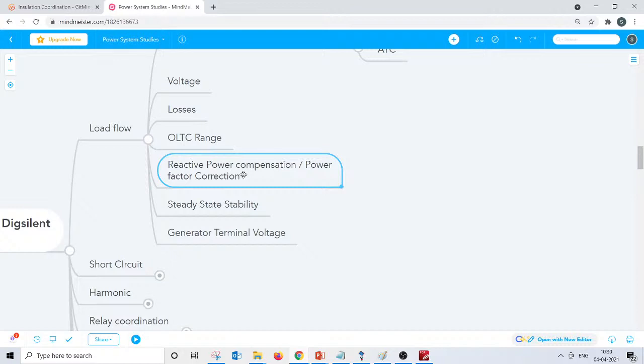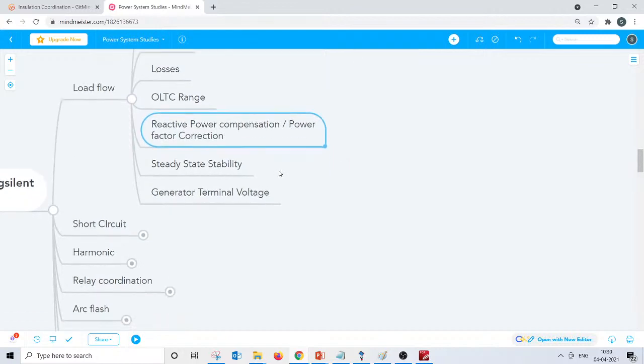Approximately, if you have 4 or 5 kilometer cables, it injects a huge reactive power in the 400 kV. So probably you need to make a note of it. We have done quite a lot of assessments on various reactive power compensation studies, especially for solar plants where the penalty is extremely high.